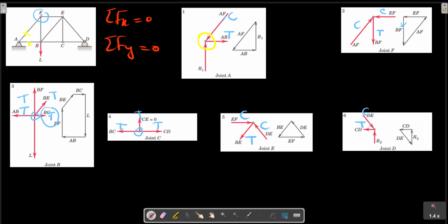Sometimes we cannot initially assign the correct direction of one or both of the unknown forces acting on a given pin. If so, we may make an arbitrary assignment. A negative computed force value indicates that the initially assumed direction is incorrect. Internal and external redundancy is the next section.